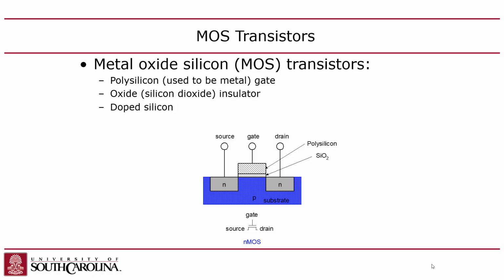Surface. So then you end up with diodes here. If you ground the substrate, make sure that this is electrically grounded, then you're guaranteed to always have a reverse bias. You won't ever have any current go between these two guys, right? Because this is a diode and this guy's at ground. So by grounding the substrate, you guarantee that you're always reverse biased on these two islands. So these two islands are electrically isolated from their substrate, even though they're touching one another, right? But they're not connected electrically, right?